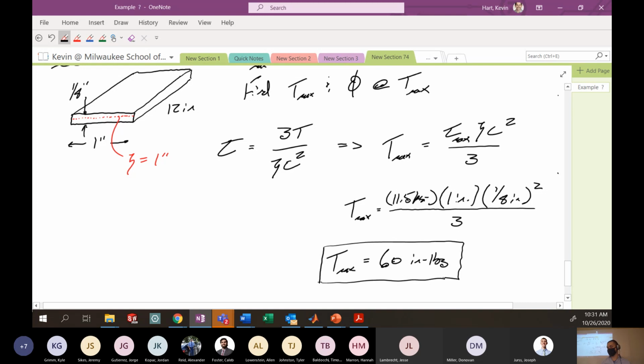So you got this like pretty strong piece of steel here. You know, you consider steel a pretty strong piece. If it's an eighth inch thick, you're going to torque this thing. It can't really handle very much. All right, open cross sections, not so good in torsion. All right, just telling you.